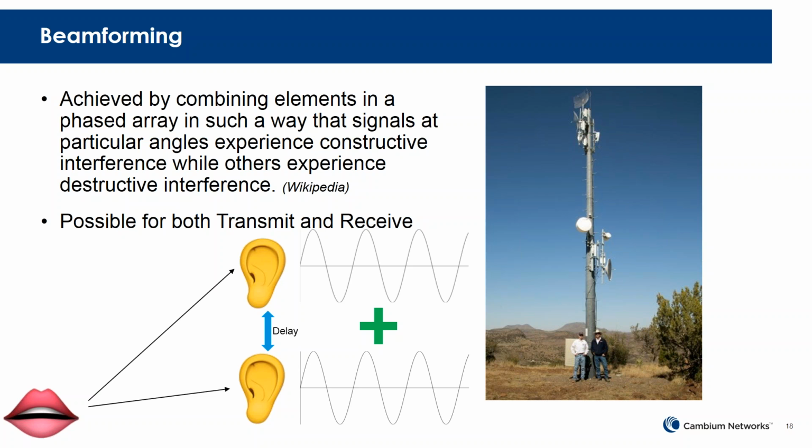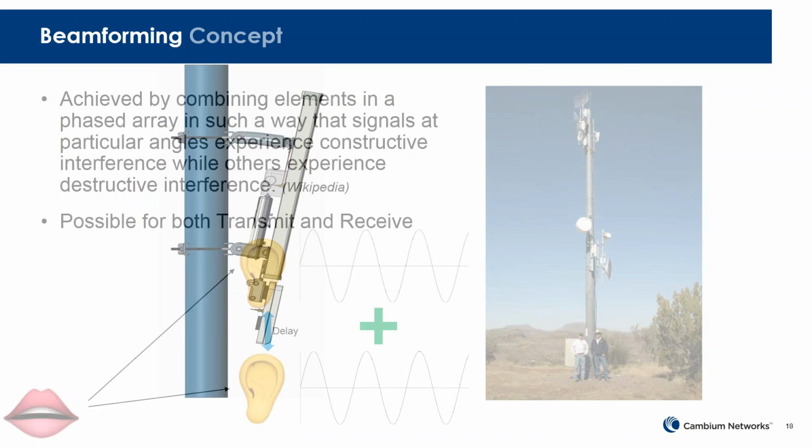And this phase shift that we do also has this effect of noise canceling type phenomenon that I mentioned earlier for any signals that happen to be coming from a different angle than the one that we're tuned to. So the combination of any signals becomes destructive at that point. In essence, we're creating a beam of directed listening to a specific area. So let's look at how that might work with outdoor radios, for instance.